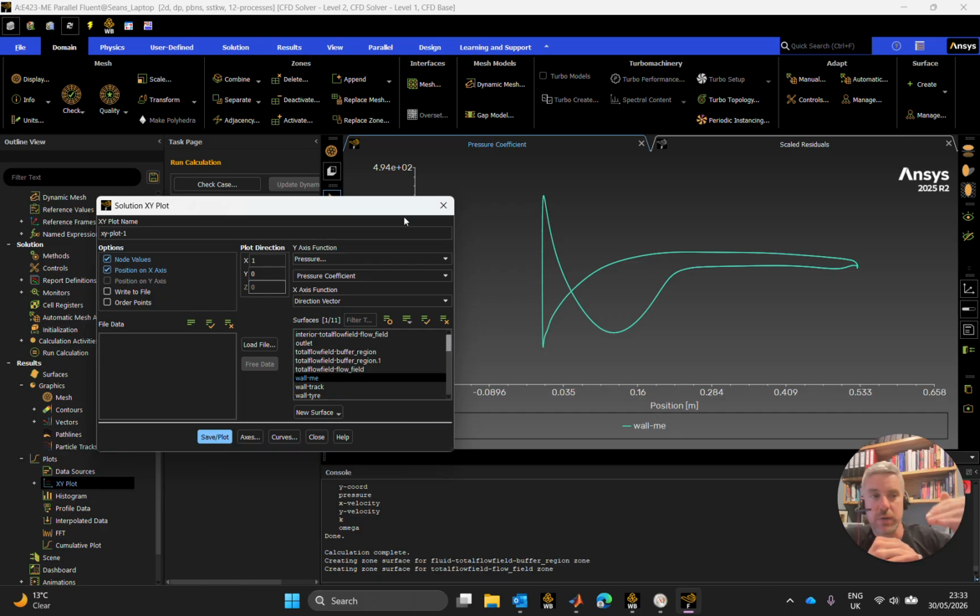But I'd like to see, if I tuck the angle of attack down slightly, is the amount of energy that I'm getting at my trailing edge higher or lower? Like what is happening to the energy as I change my angle of attack, as I drop it there? Because maybe I might want to keep that Eppler E423 airfoil flatter and then let the flaps take up that sort of angle of attack.